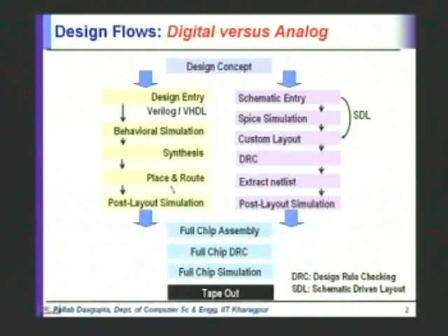Okay? And often this routing is done across the parts which are designed by separate designers. So again that is a non-trivial task, and the shape of the different blocks, their placements and the routing is all an integral problem, because if you place them badly then you will not be able to route them properly. If you place them properly, you are able to reduce the amount of interconnects to connect them.